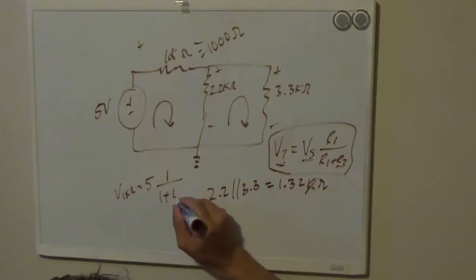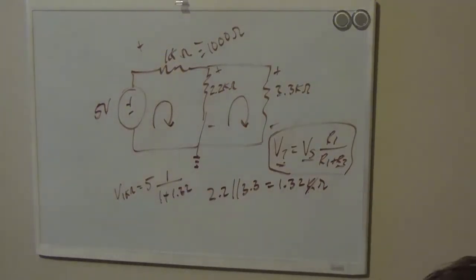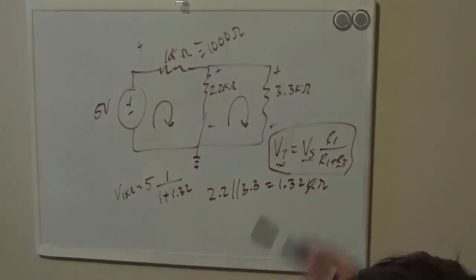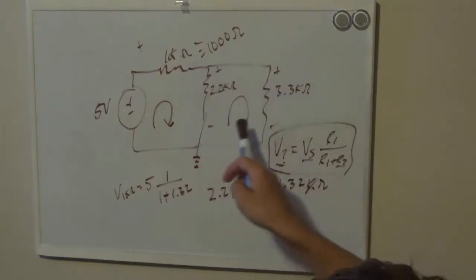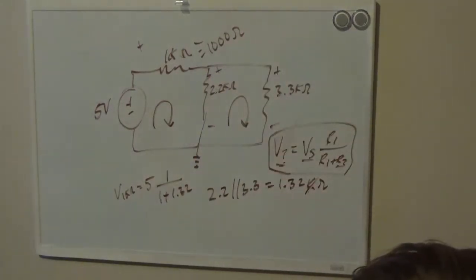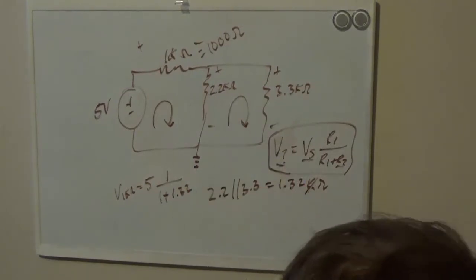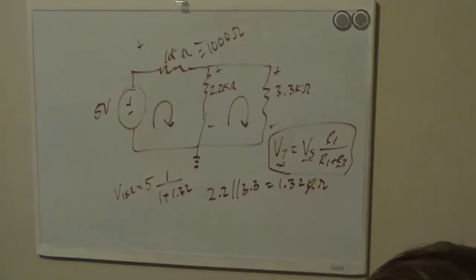So that's where we now add this term into the equation. Hopefully this makes sense to you why that works that way. Like I said, it has to do with the fact that these are electrically connected and the current can take 2 paths. Since the current divides and takes 2 different paths, that means that these resistors are in parallel.